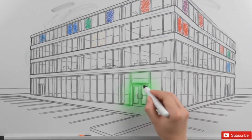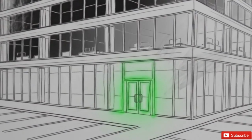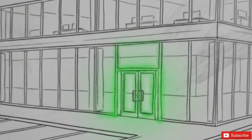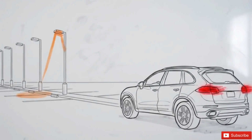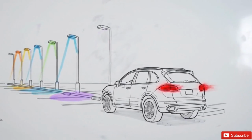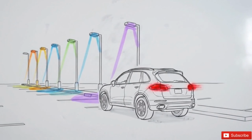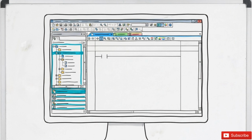Imagine closing down a commercial building for the night. The main interior lights must shut off, leaving a single exit door illuminated for exactly 15 seconds. Only after that delay is complete should the exterior parking lot lights activate, and only if a vehicle is actively pulling out. Automating this sequence requires a program that can manage multiple timed delays and conditional triggers without any human intervention. We will build this system from scratch in Siemens TIA Portal.